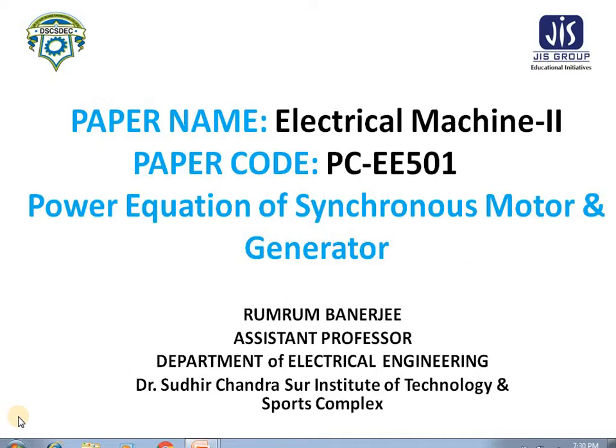Before starting with the equation, I will highlight the principle of a synchronous motor. Basically, consider a 2-pole synchronous motor with AC supply given to the stator winding. A rotating magnetic field is produced in the air gap, which rotates at synchronous speed. The three-phase supply here gives a rotating magnetic field.